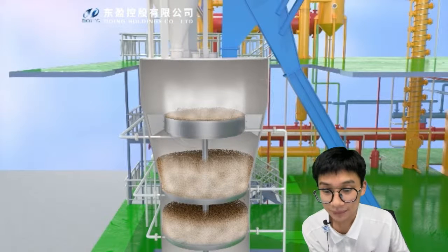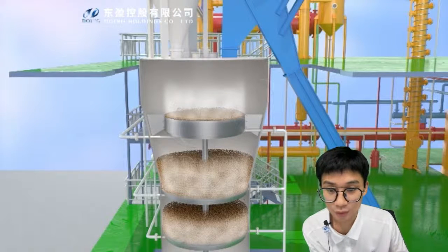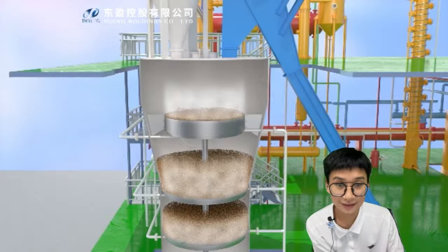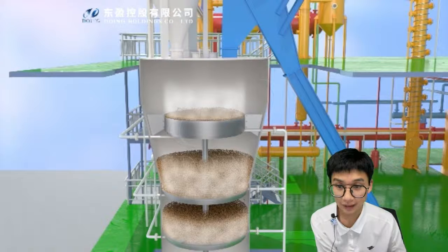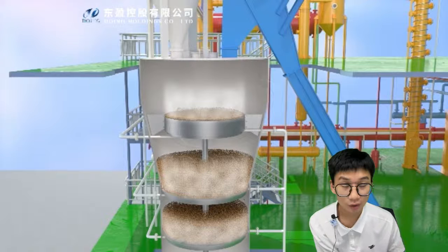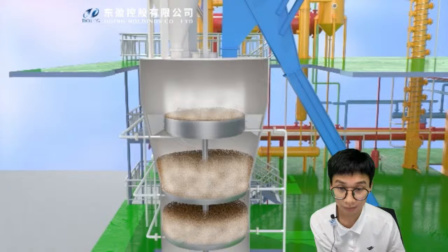And the DT is mainly divided into 4 different process layers: pre-desolventizing layer, desolventizing layer, direct steam layer, and energy saving layer. The pre-desolventizing layer is also called the tray layer. Usually it is layers 1 to 4, and the main function is to preheat the wet meal properly, remove the solvent, and reduce the moisture in the meal.